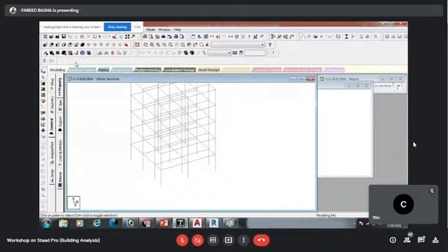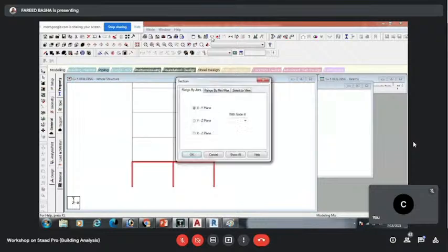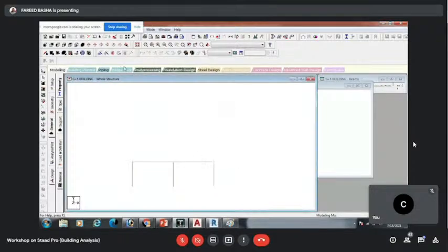And then again I'm going to select what type of structure I just want to see. So select the beam option, select only these beams, select the cut section option, and select section view highlighted only. Okay. Then select 4 node plate. First I will create one slab from these 4 nodes, like my rooms. After that I will create one only for my balcony.